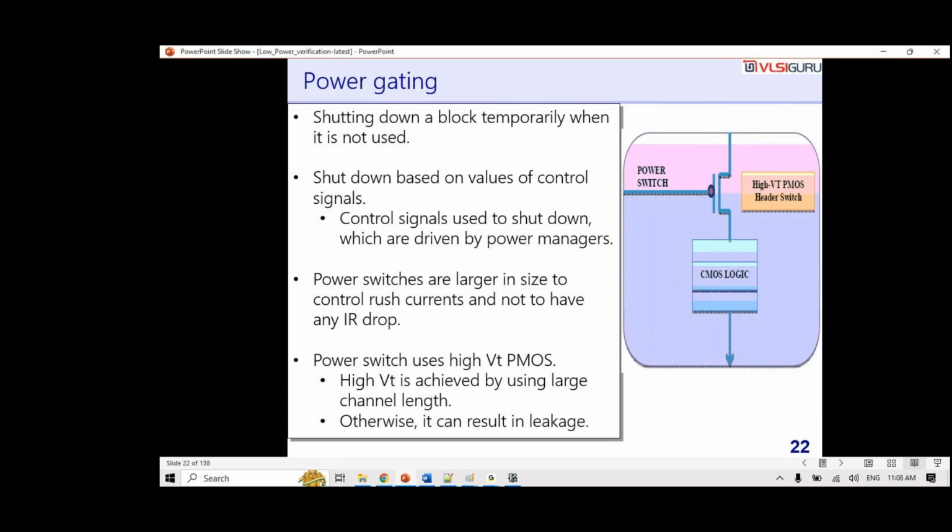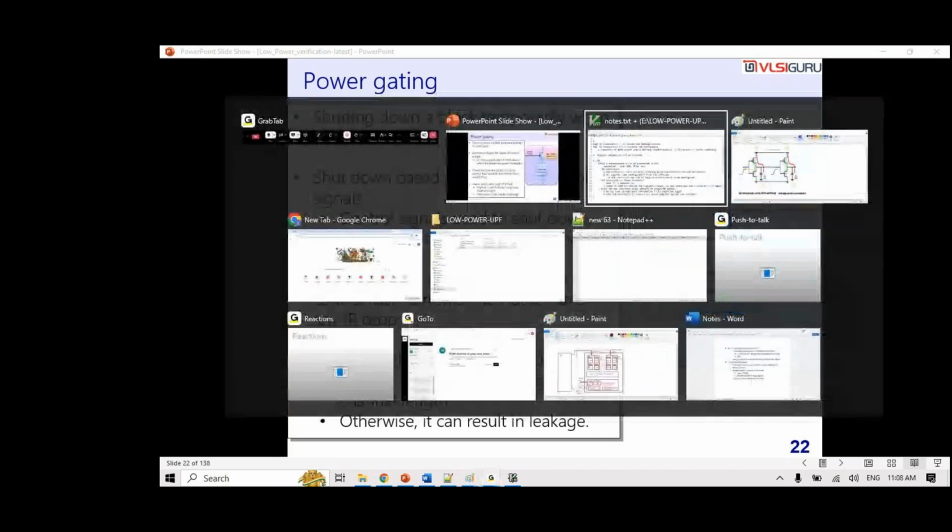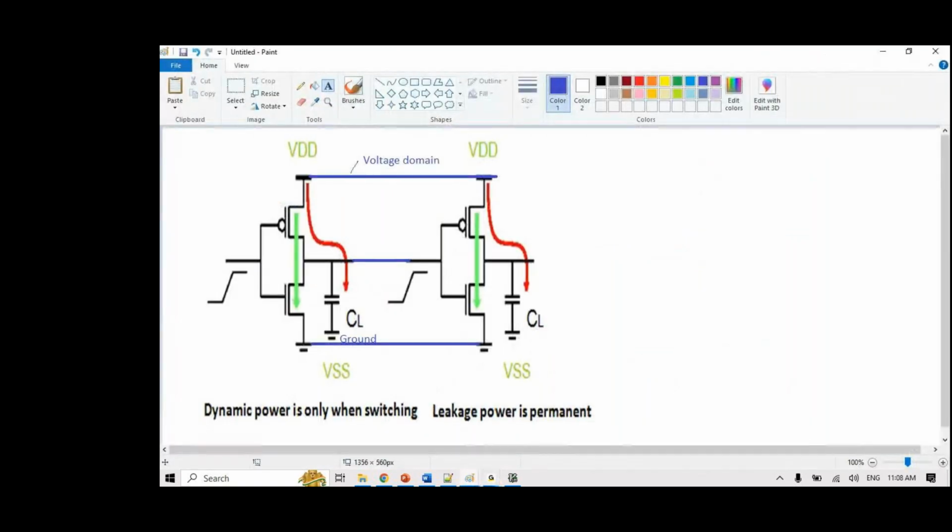So we are talking about the entire power rail being controlled by this one. I mean, top layer power rails. Yes, top VDD is connected to this one. There will be so many VDDs, right? The voltage distribution will happen. What I'm talking about here is that here you will use a power switch.